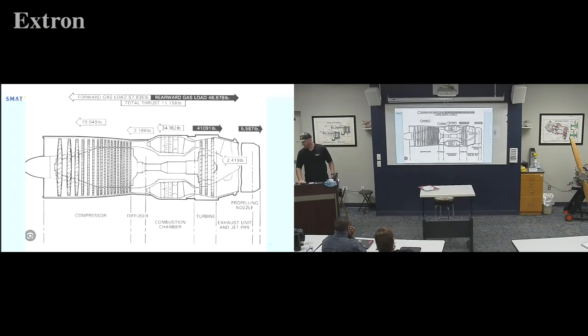Nope, it's not. So anyway, normally we're going to have one thrust bearing, but that bearing is not going to be holding, let's say, a 20,000 pound thrust engine. The bearing's not holding 20,000 pounds of thrust. It's going to be a small fraction of that typically. A lot of the other forces are going to be acting on the stators into the case of the engine. So it's actually the case of the engine through the stators that's trying to move forward, not just that shaft trying to leave it. So that was mostly what I was trying to get out of that one.